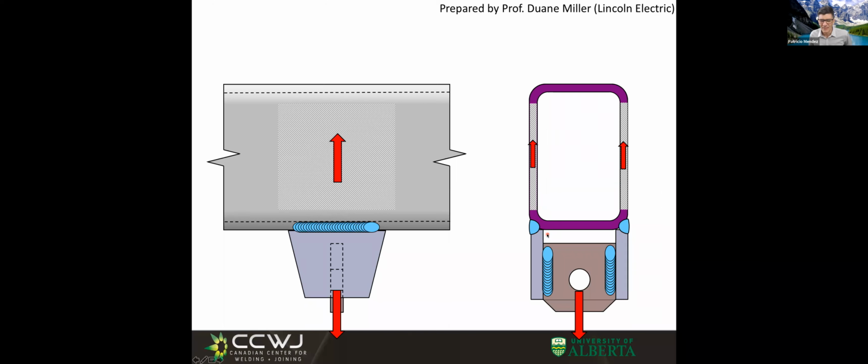And again, for example, I don't like seeing these gaps here. But you know one of the reasons why people leave a gap? Very often they design the gap because if they don't put the gap, the welder will want to weld it. Because when you see something that is in what you think is the path of the load, you think the load goes from here to here. But no, it doesn't. But when you see it in reality, not in this abstraction, you feel really, really tempted to weld it. So very often they leave this big gap, so the welder doesn't succumb to temptation.